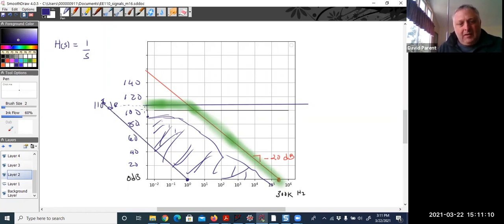These lines are parallel, but eventually it'll stop working when 1 over omega is greater than the open loop gain. So in this case, the limitation is really at low frequencies, and it's that the open loop gain just isn't infinite. This will still work as an integrator though, by the way. But that frequency range will work here.